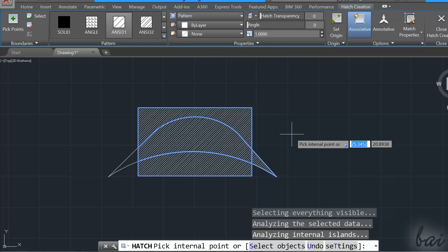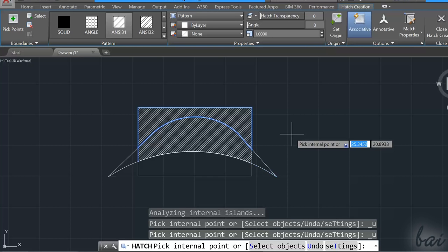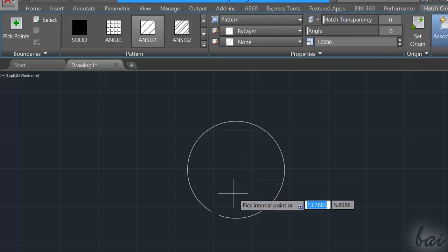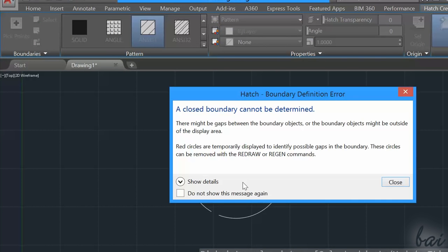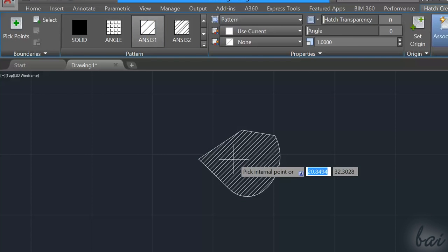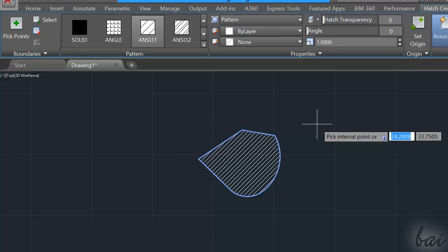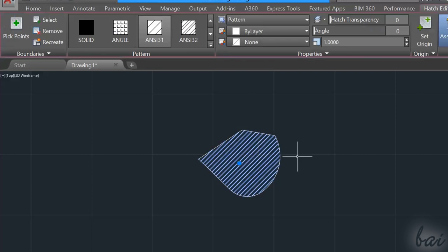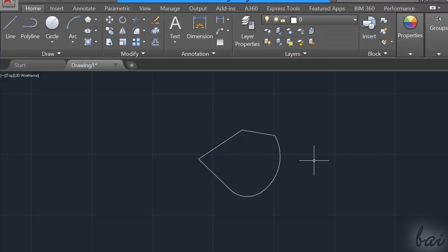Use Ctrl and Z to undo the latest filling applied. Use the Enter key to finish with the Hatch tool. This tool obviously works on closed paths only, where there is a finite area defined. Fillings made are called hatch objects and share the same shape of their boundaries. You can delete them by selecting them and using the Delete key.